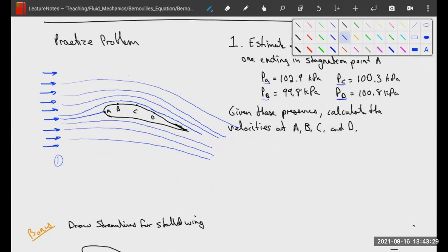So we're going to have our static pressure, our dynamic pressure, and our pressure due to the height within a fluid. So we have P1 plus 1/2 rho V1 squared plus g Z1 times rho is equal to P2 plus 1/2 rho V2 squared plus g Z2 times rho, right? So what's amazing about this is we're going to have to do a little bit of shenanigans here.